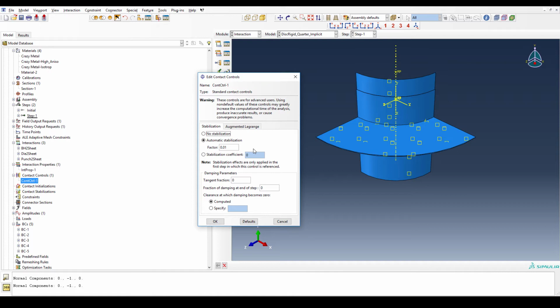So at the end, the stabilized implicit simulation is still much faster than the explicit one, which makes sense, because this is the reason why you still want to do implicit, other than, let's say, the physical accuracy. But in these quasi-static environments, your explicit solver will also lead to fairly accurate results, unless you use a very high mass scaling, of course, right?